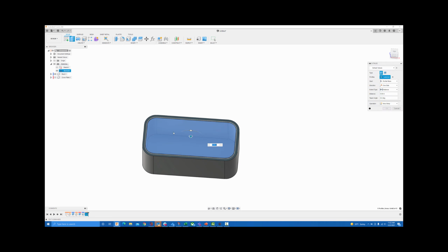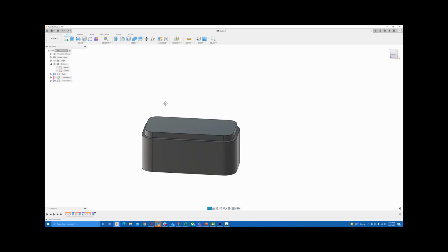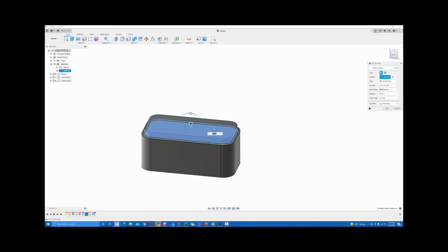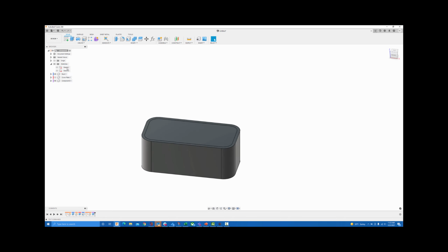So if I grab that and extrude that down in, we'll say 0.25, and we're going to create that as a new component as well, although I went the wrong direction. So let's come in and just do a minus there. So now it's flush. And then probably one last thing, I want to put some holes there that we can put a piece of glass in.